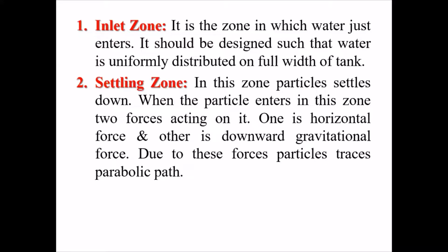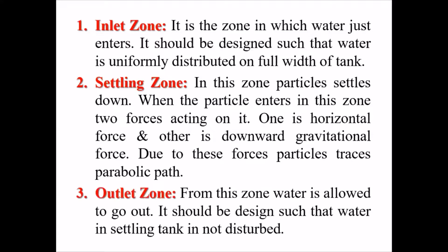When a particle enters this zone, two forces act on it: one is a horizontal force and the other is a downward gravitational force. Due to this, particles settle at the bottom of the tank. Then the outlet zone: from this zone, water is allowed to go out. It should be designed such that the water in the settling tank is not disturbed.